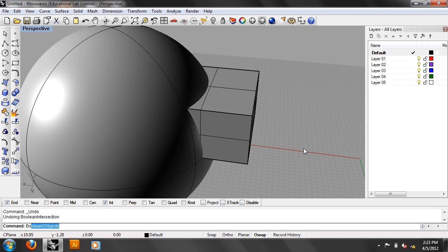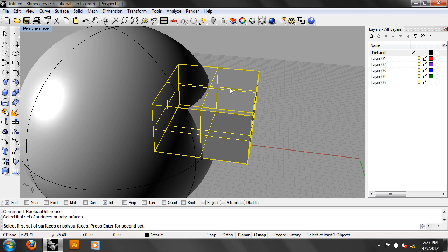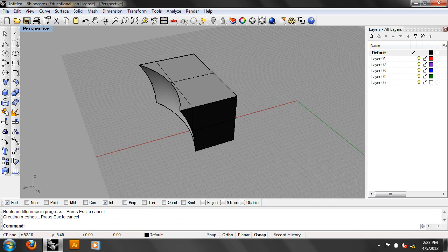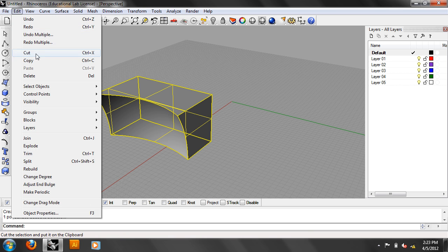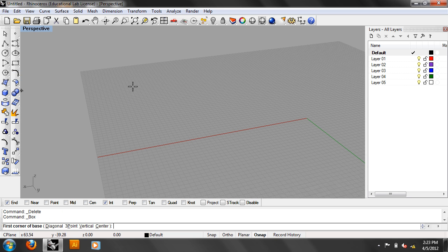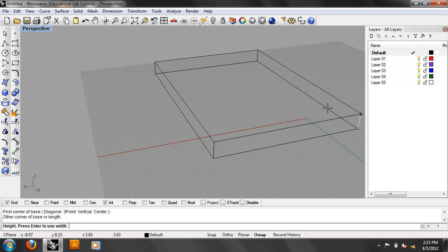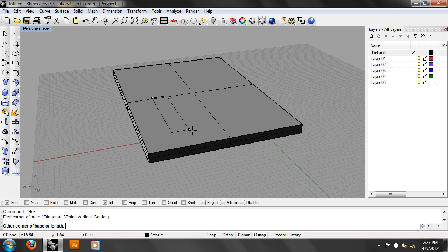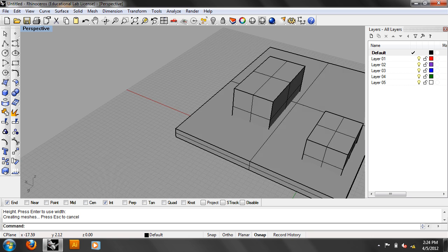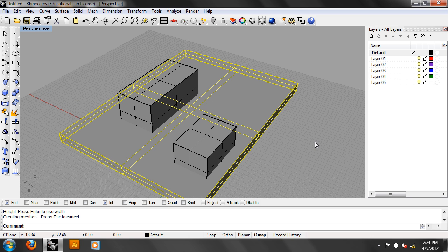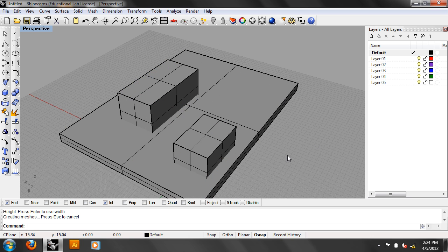And then lastly, let's do Boolean difference. You select one object, and then a second set, and it will remove it. And you can do them in different orders, and it will remove the piece. So that's the one that I find most useful, and that's the one that I find is most abused by people. And what do I mean by that? This is what I was talking about before, when the way that people make facades is that they have a lump of gingerbread, and then they have these boxes, and then the way that they make their facade is they do a Boolean difference.